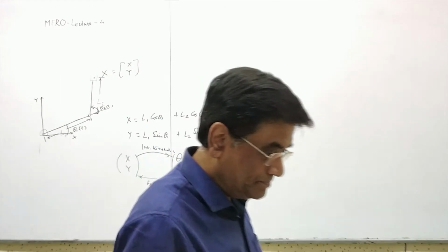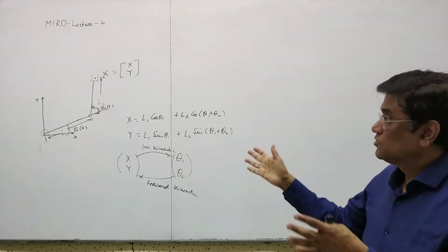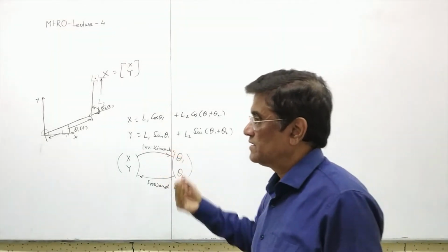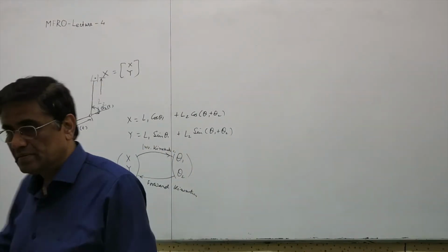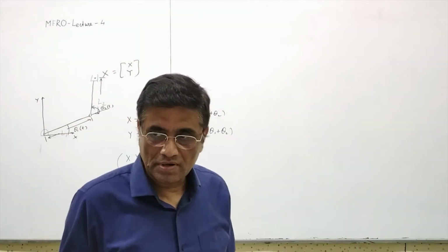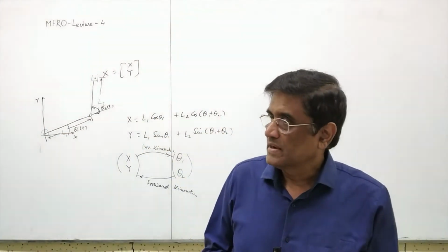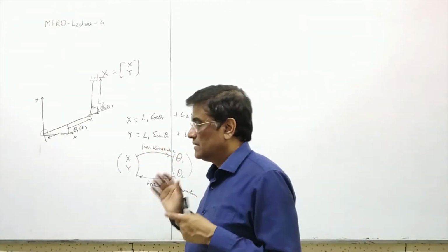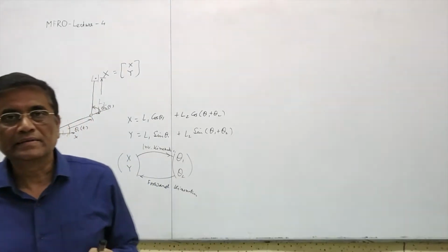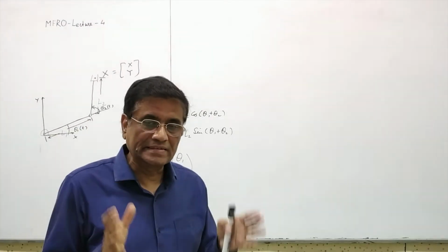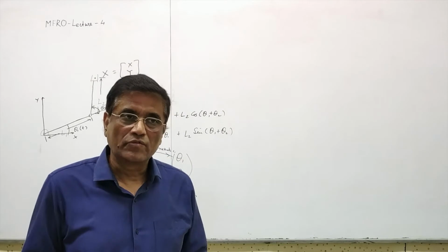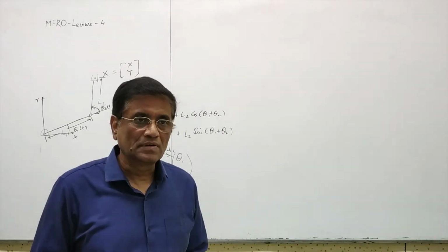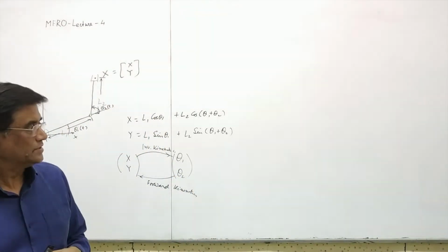Why? Because the robot needs to know where its current position is. Say the robot is switched on for the first time. Whenever you switch on a robot, for example an industrial robot, it makes some sound and it has an execution level controller. It tries to figure out its home position, which is defined for the robot where each joint takes some value. Okay, so that is called initial position or home position of the robot.